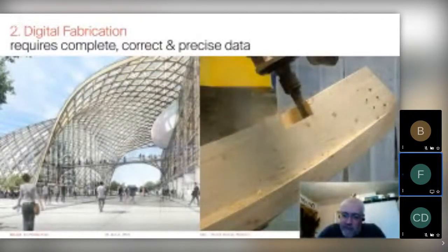If you have intricate detailing with steel dowels or pre-drilled holes for screws or whatever, your engineer is going to tell you that they have to be within a certain tolerance to be ticked off in the end and approved. So the machines are capable of very precise work, which means that they will reproduce every kink in the digital model that is bigger than the production tolerance of 0.5 of a millimeter in the material.